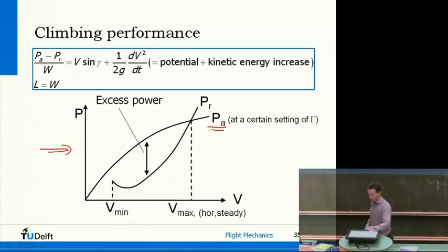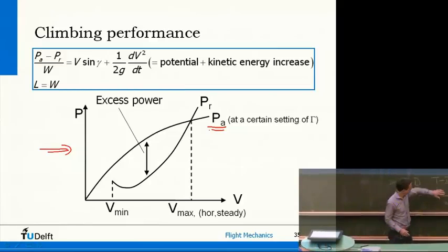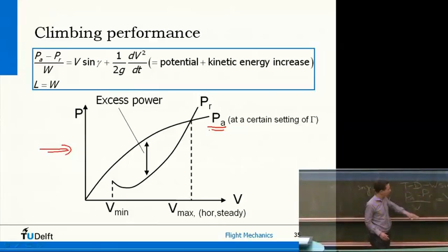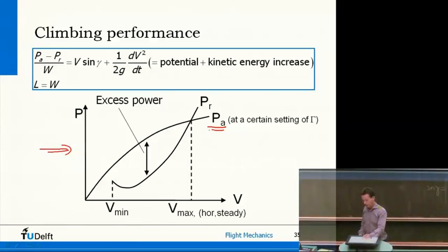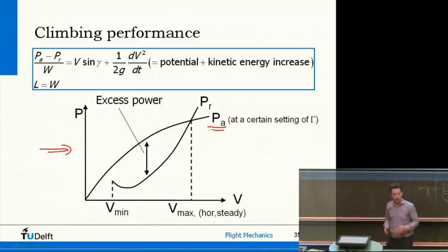This power available curve can look like anything basically, but it will always start at 0 because you have 0 velocity there. But what you see, if you make a diagram like this, and this could be the most general case for a given aircraft, is that this difference you draw here between power available and power required, that's basically this measure here. So that distance tells you how fast you can climb. So you can see straight away that if you fly very fast, then you cannot climb that quickly. If you fly very slow, you cannot climb that hard. And somewhere in the middle over here, where the curves are the furthest apart, that's where you can climb the fastest. That's where you have the most energy in excess.